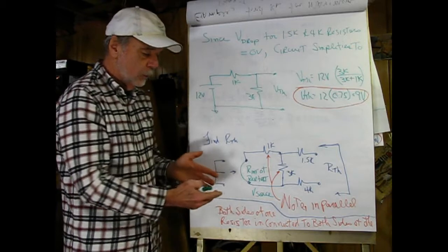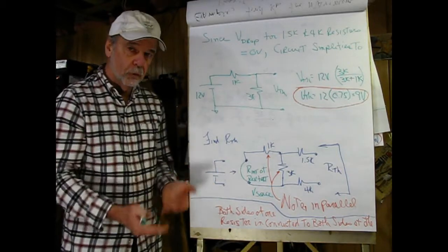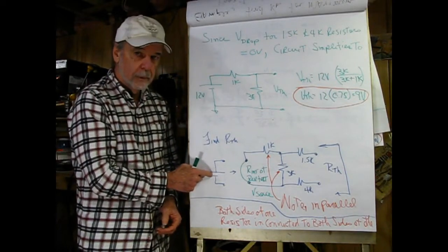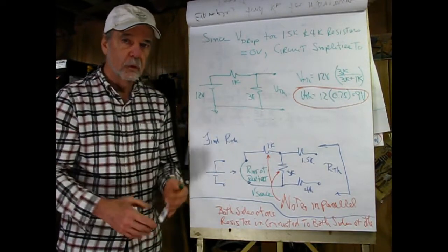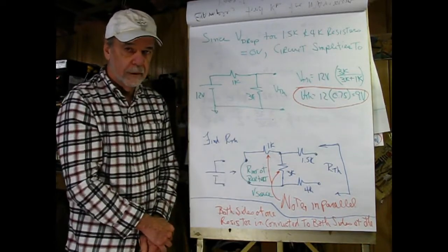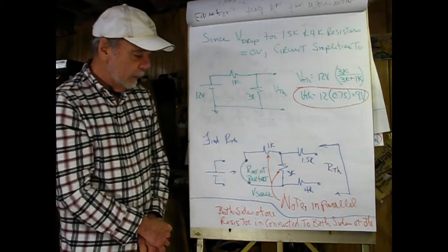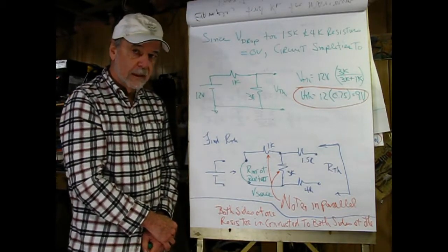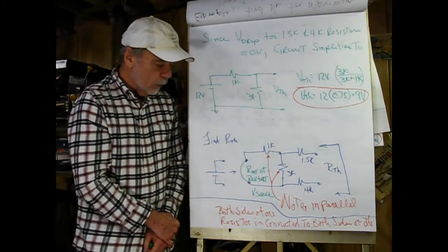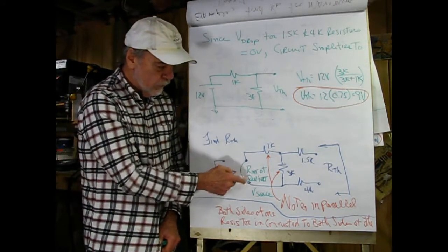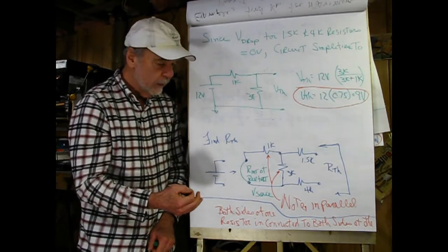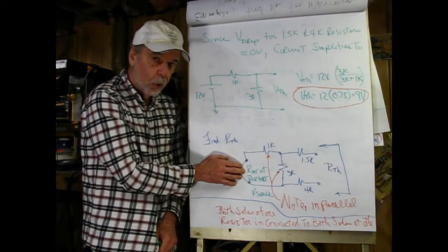Now realistically, when we started this, I said that all sources have internal resistance. However, suppose that this is a car battery with an internal resistance which is incredibly low. Well, relative to our circuit values here, we can eliminate that from the calculation. And a lot of batteries or cells, like a lithium-ion cell that is fully charged, that is in fact the case. So we're going to replace this here with its internal resistance. A voltage source is going to be 0 ohms, a short circuit, and with a current source, it's going to be an open circuit.